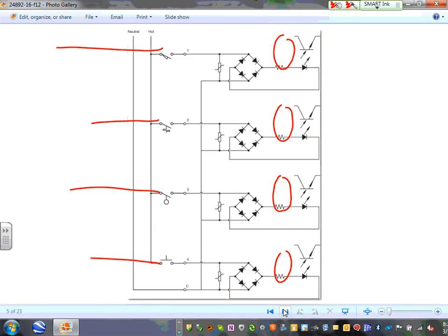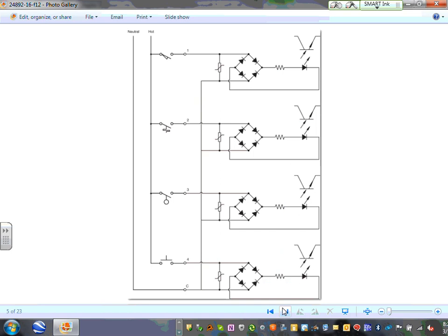All right, so here's how they do them. The programming. I want you guys to pay attention to this because that's what the next chapter will talk about. Look what happened here. We're bringing an input from a limit switch, a thermostat, a float switch, and a push button. All these are inputs coming to the PLC, right? So when you close, look what happened, guys. When this closes, here's 120 volts. You bring 120 volts right in here. You convert this into, say, 24 volts right here. This will create a light.